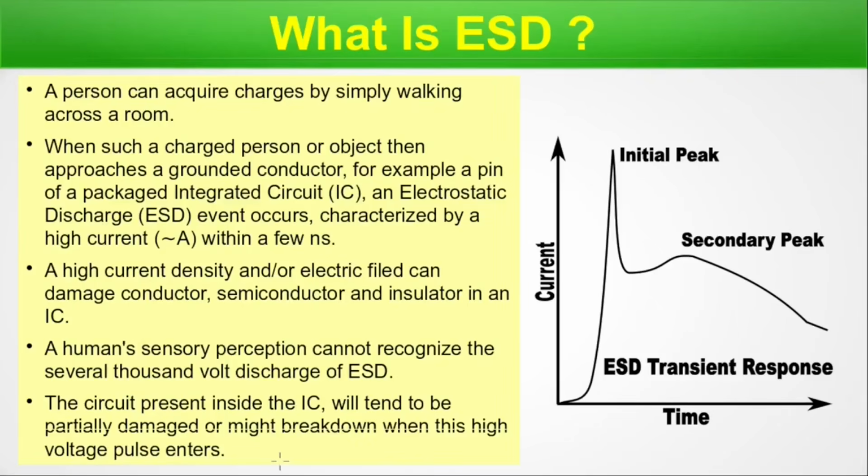Now there is another thing you can notice in day-to-day life: whenever you purchase a RAM or a hard disk, you get it in a bag which may be graphite in color. Those bags are electrostatic proof bags, inside which the hard disk or the RAM, all these semiconductor things or computer equipment, are packaged safely. So those are also used in the industry for protection. Those are external protection. However, in today's discussion we will talk about the internal protection. That means a circuit should be internally protected from external ESD injection.